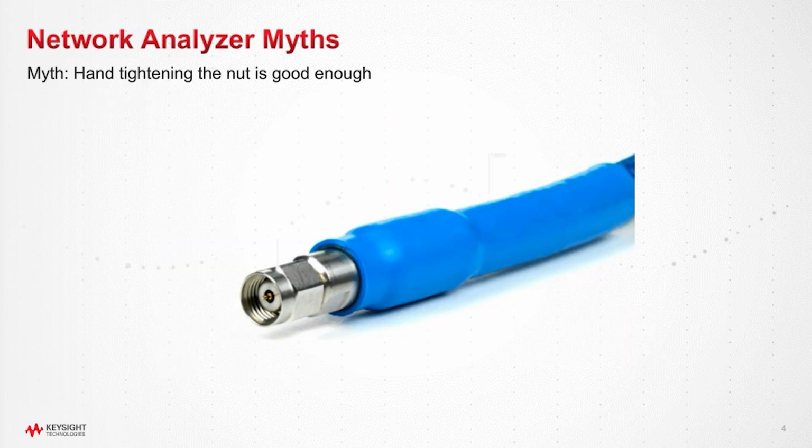When you're connecting an RF cable like the one you see here, there's a nut at the end of it that you have to screw on to the connector on the other device. One thing you may hear in the lab is, oh yeah, if you get it as tight as your fingers can turn it, then that's about 0.8 Newton meters. And that's just not the case.